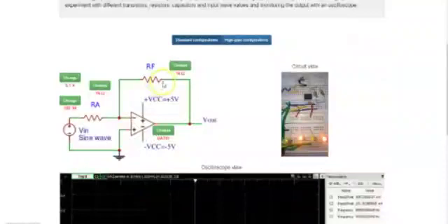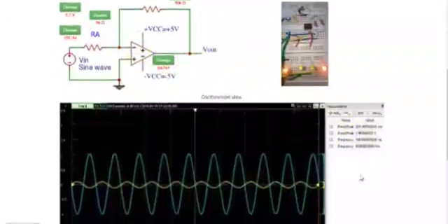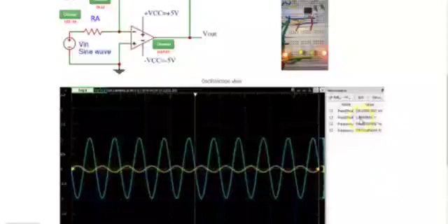Let's start the analysis with Ra of 1 kΩ, Rf of 10 kΩ, voltage of 0.1 volt and frequency of 100 Hz with 741 op-amp, which has relatively lower performance parameters. With the input sine wave frequency as 100 Hz, observe the peak-to-peak amplitude of input and output are 1.99 volt and 203.40 mV respectively, thus confirming gain of 10 in magnitude. The output signal is 180° out of phase with that of input.